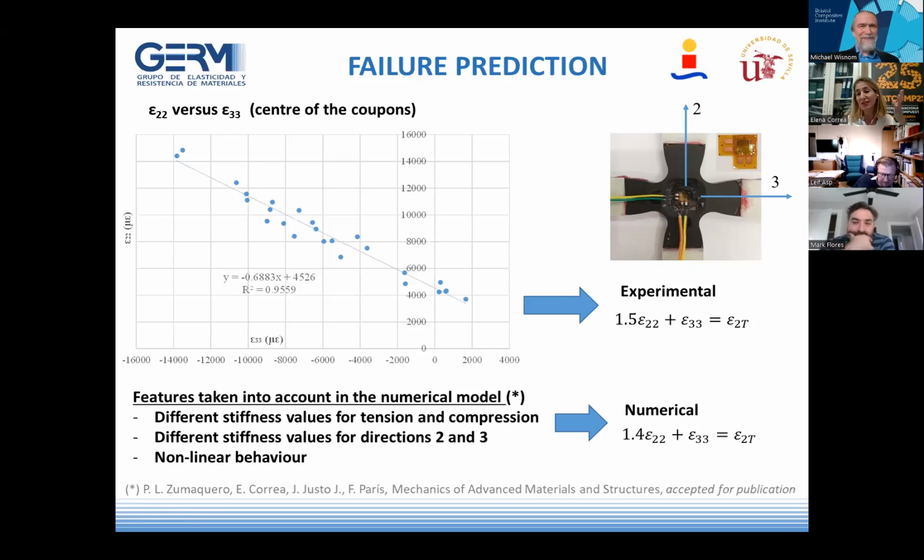Perhaps I should say that the way in which the specimen transmits the load, or the stresses, changes a little bit from the outer ratio. I mean, if you have, for example, transverse tension in the vertical direction and nothing in the horizontal direction, you will find that in the center of the specimen there is a small compression. So there's a slight shift of the curves from one state of stresses, the external state of stresses, to the inner one. That's the difference.